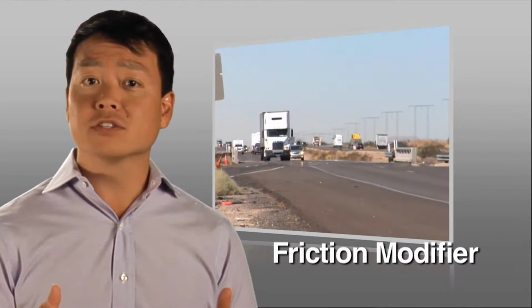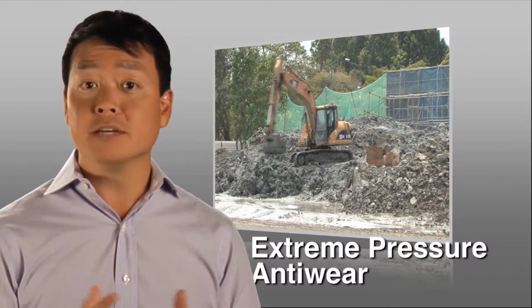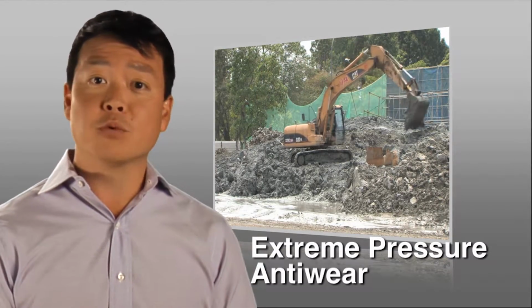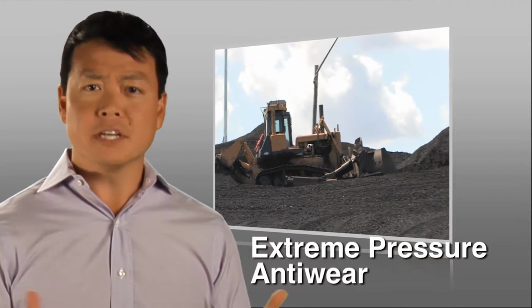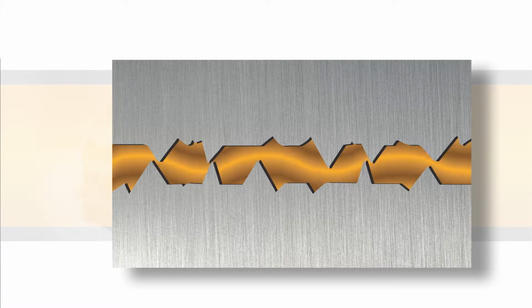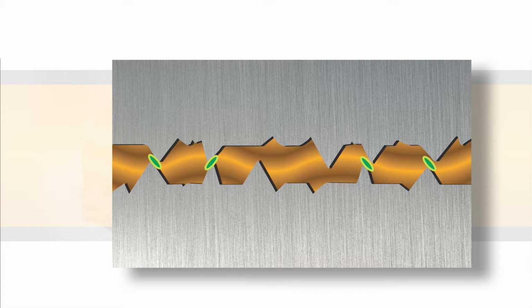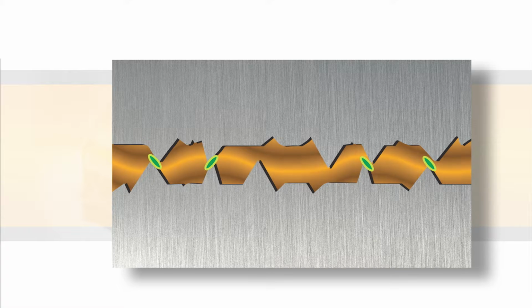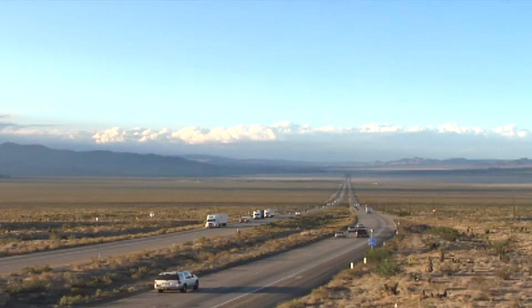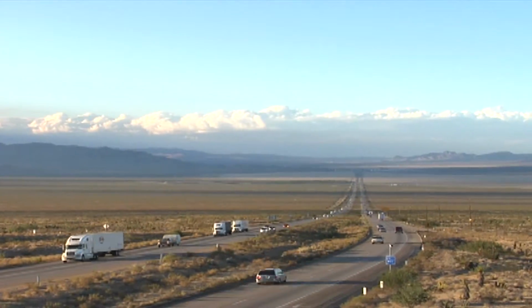The friction modifiers reduce friction and wear during mild sliding contact. Under heavy and medium loads, the extreme pressure and anti-wear chemistries replace the friction modifier. These two components are typically used in combination. They react with the metal to create an easily sheared surface layer. If any asperities do touch one another, they shear cleanly rather than breaking off. This doesn't create metal debris particles. An additive package with all three components provides protection under the full range of gear contact pressures.